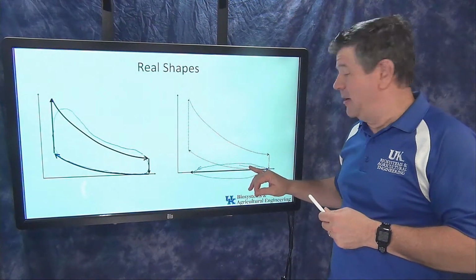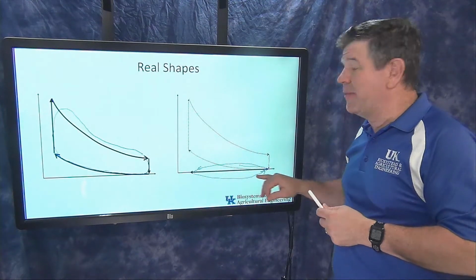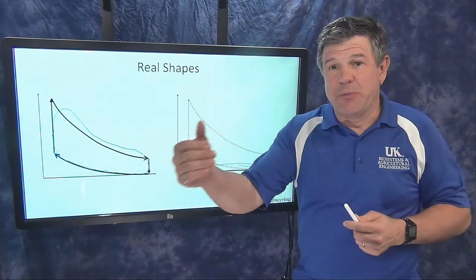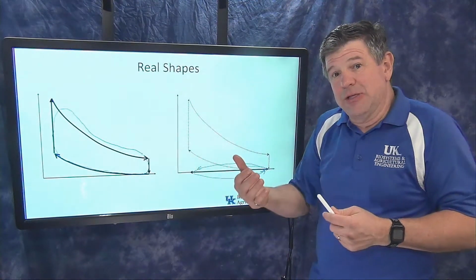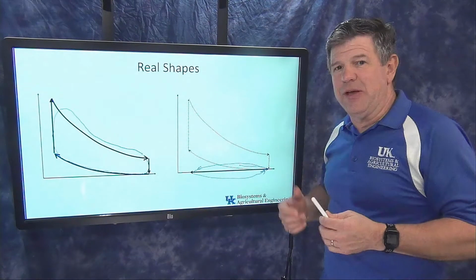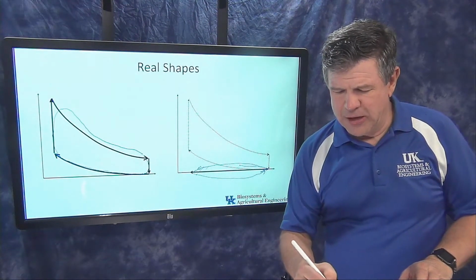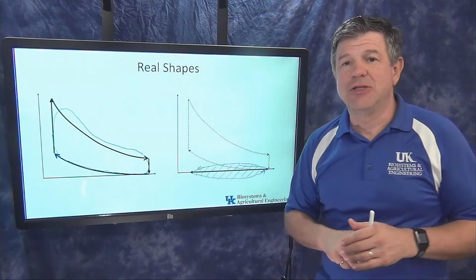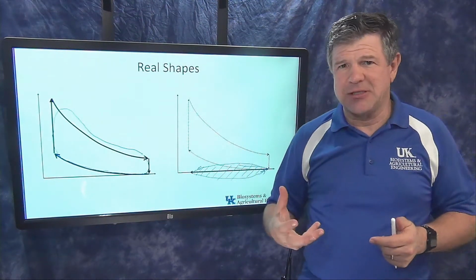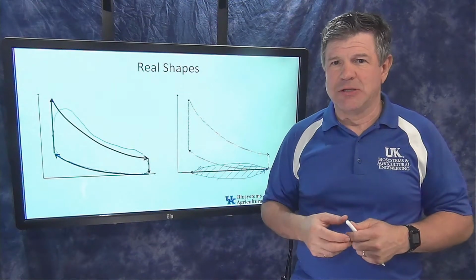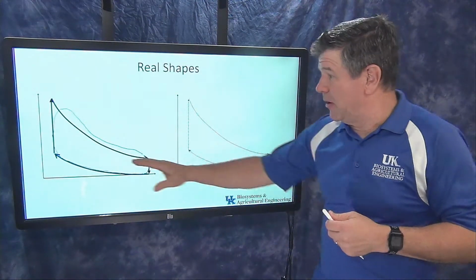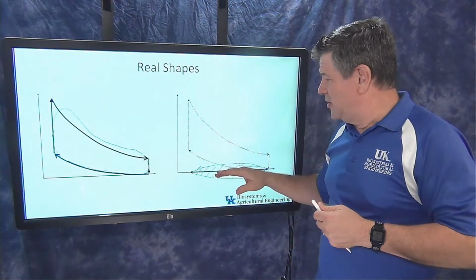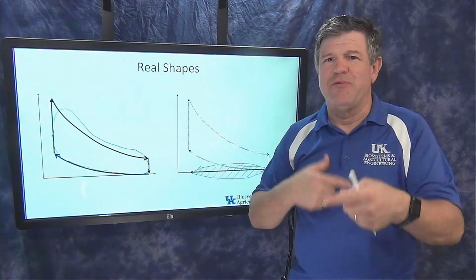Oh man, what's happening? On this loop, I'm going to have some energy loss, right? So it takes energy to push that gas out. It takes energy to pull the clean stuff in. So there is going to be some energy. This is a loss. So that's energy that I have to put into that piston somehow just to keep the system working. Now, it's a lot smaller than the energy I get out of the fuel to do useful work. And so this energy really is technically coming from the flywheel on your engine.